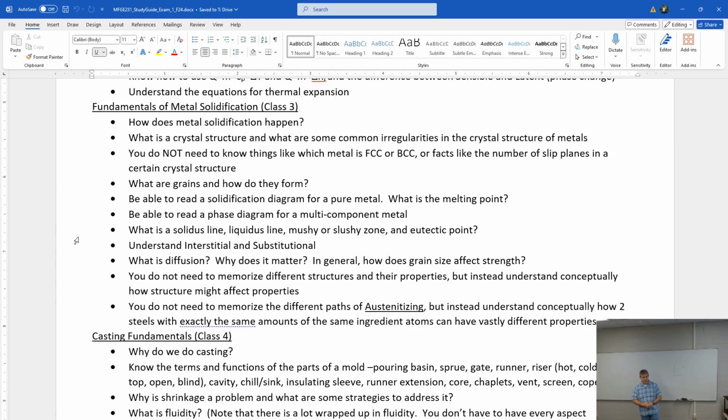The other place is in composites, where if you're putting the composite plug into the autoclave and you use a steel plug, the plug will grow 10 times more than the composite grows. So your part will end up the wrong shape because your plug will grow, the part will cure there, the plug will shrink, and it's easy to get off. So that's a good thing, but your part is not the right shape.